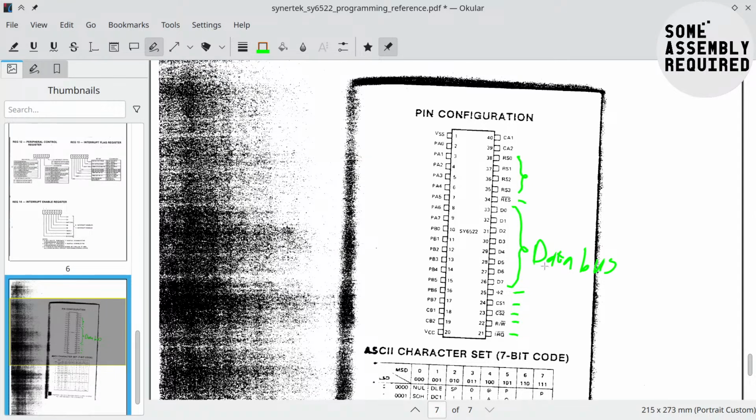What we have on the other side, the interface facing, we have 8 bits of data, and then 8 bits more of data. So that's port A and port B. And then we have control A 1 and 2 and control B 1 and 2. And these are, like I said, loaded with functionality. There are various ways we can activate them. So let's start at the beginning. Okay, let's start with the infrastructure.